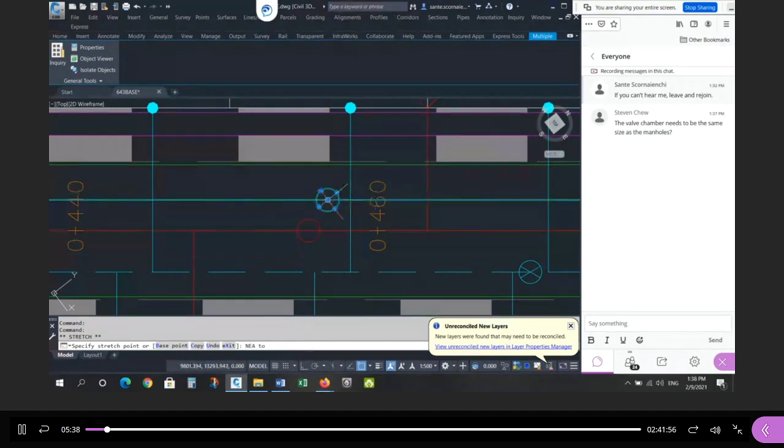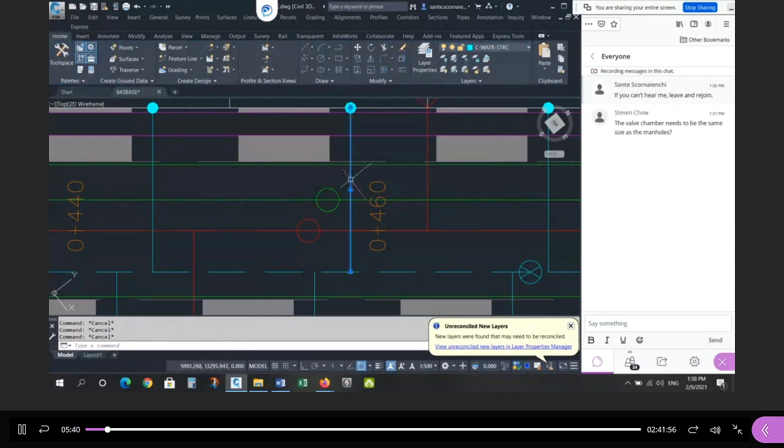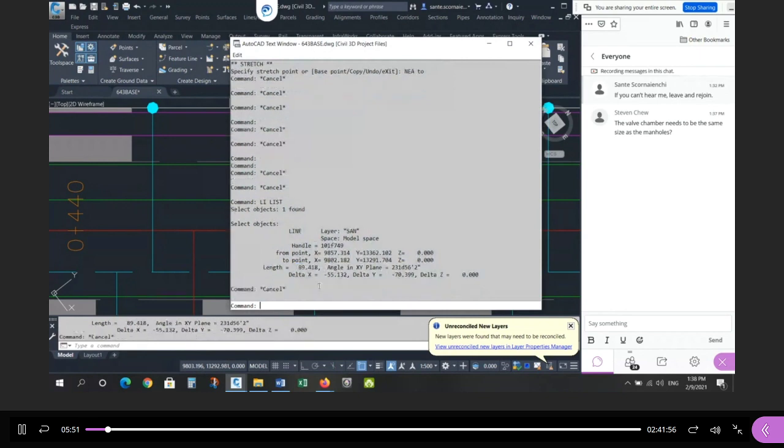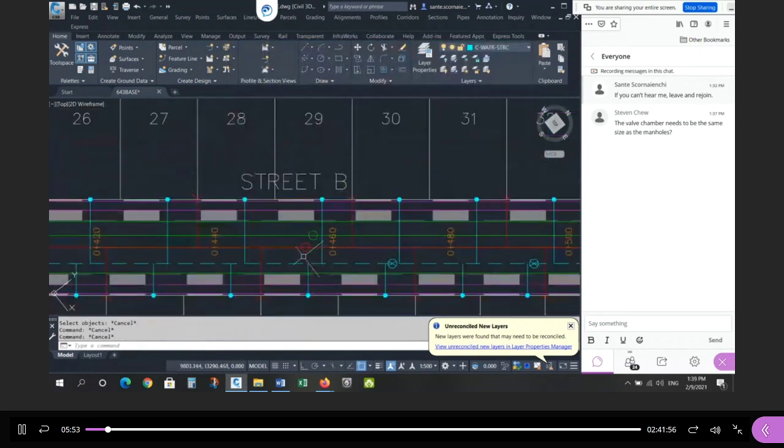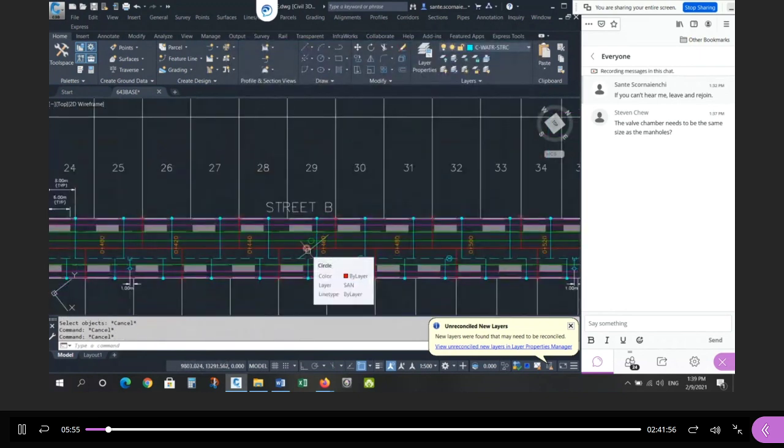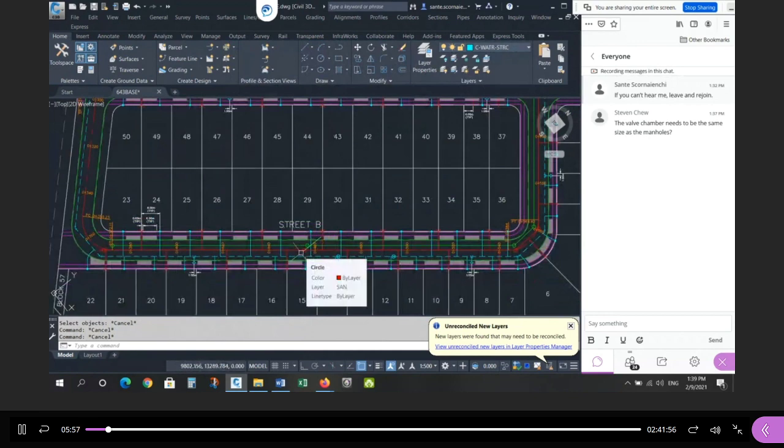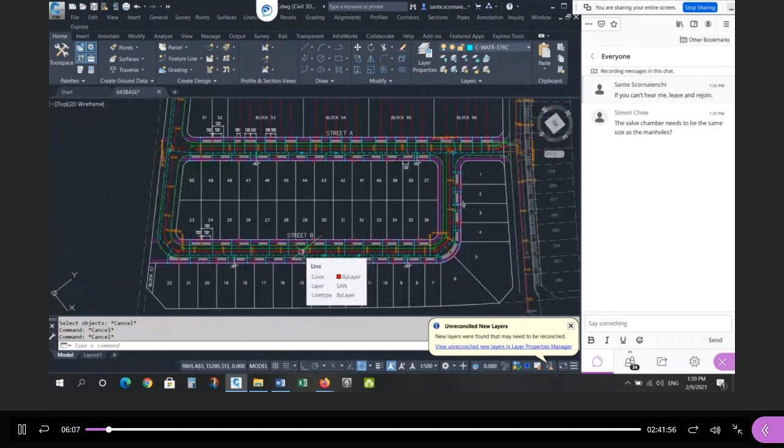So this is what I mean by, as you add detail to the design, the latest thing you're working on may be in conflict with an old thing. Okay, so that's a problem. Now I moved this maintenance hole. Let's make sure this isn't too long now. That's still good, less than 110 meters. So you're always checking, making sure things aren't going to conflict with each other. So as you proceed, you may have to revisit a previous step. And that's just the nature of the business. As you add the detail, you might find that there are some issues that you have to look at.